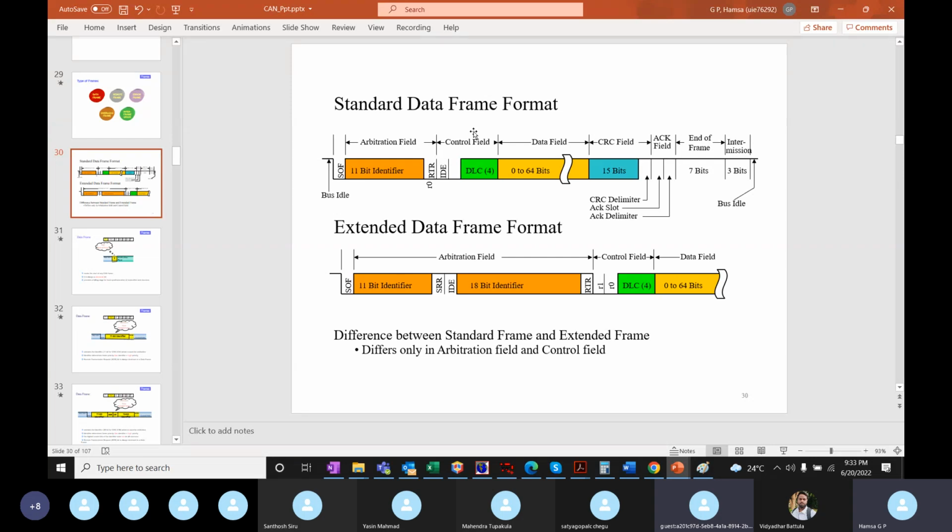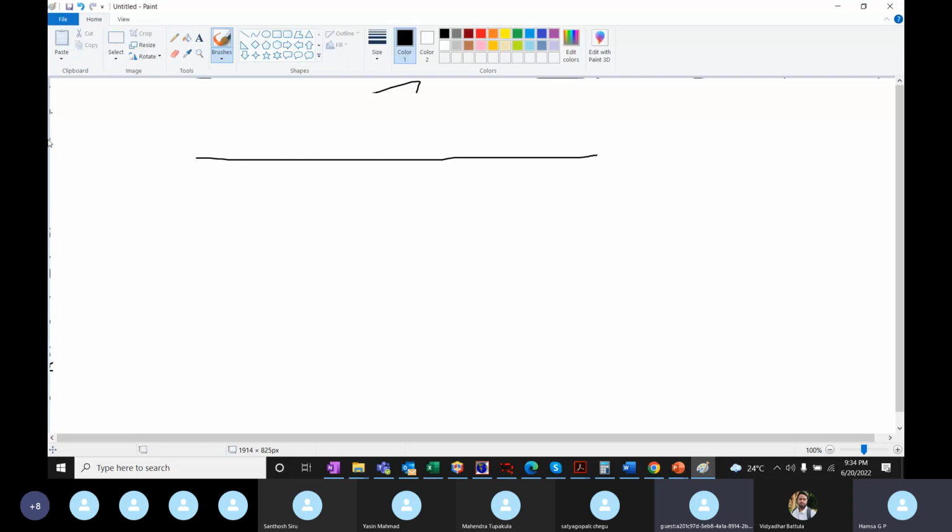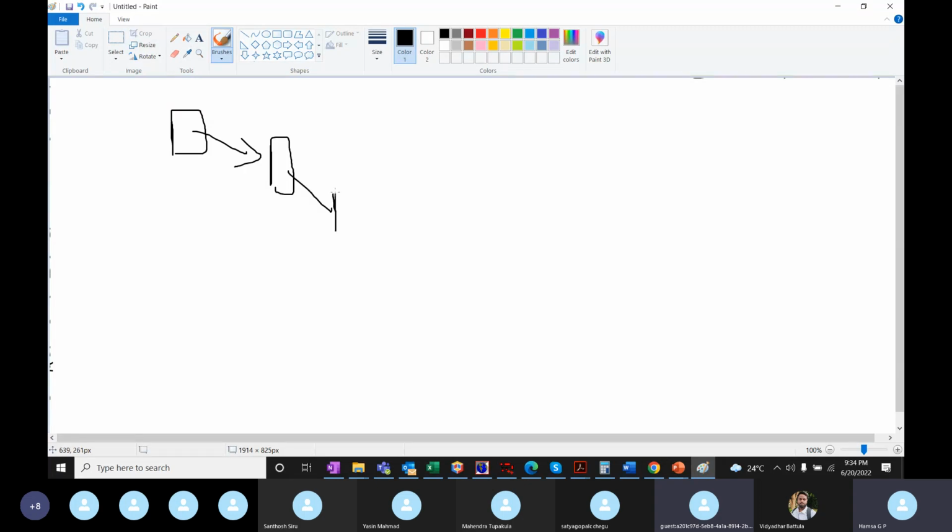Assume there is an object within 2 meters or a meter near your car, almost going to hit the front of your car. How exactly is the data sent? It cannot simply say, you have an object in front of your car, and the brake says, yeah, I can see that and I'll apply the brake. One ECU, a sensor, transmits the data to the sensor control unit, and from there it comes to the brake ECU, where the brake ECU takes the action.